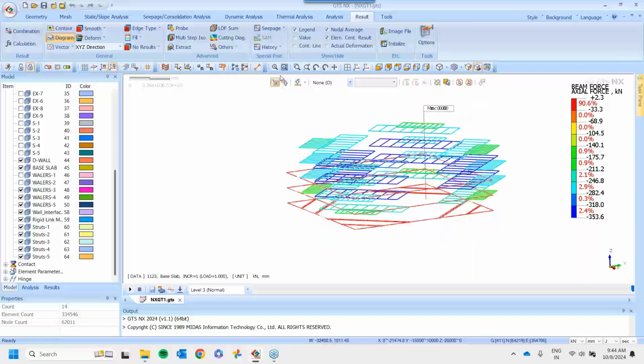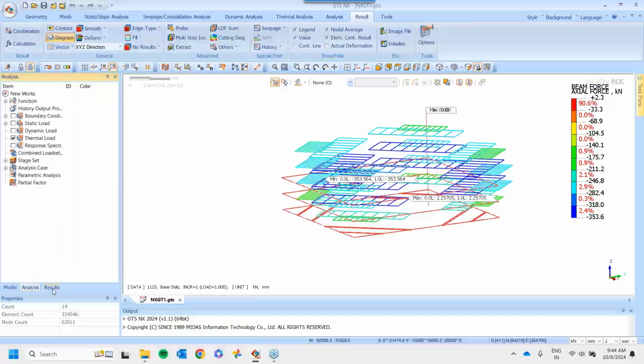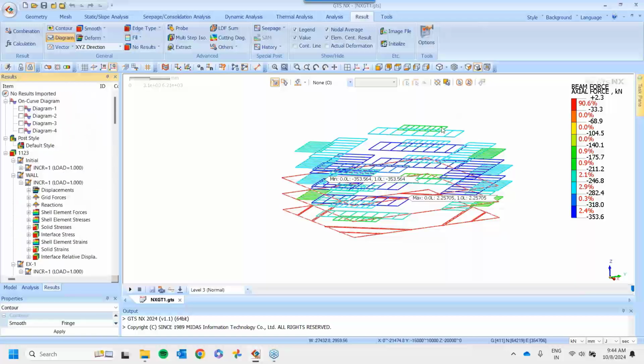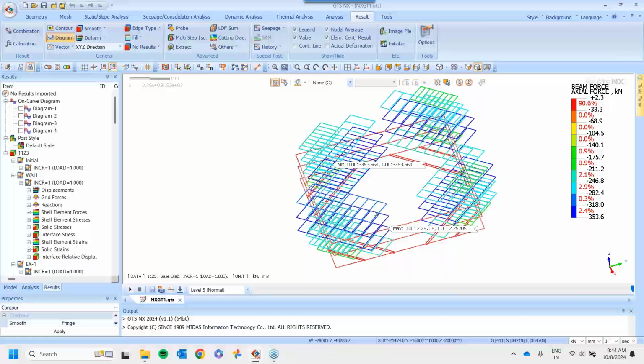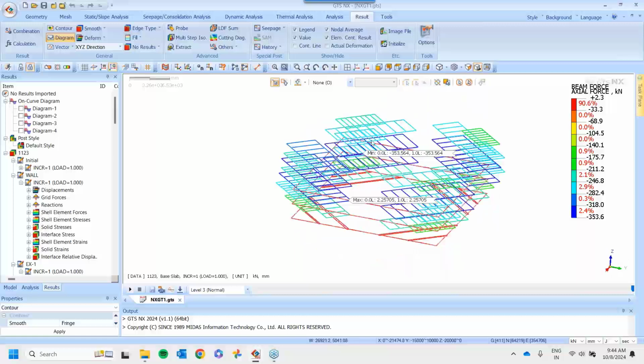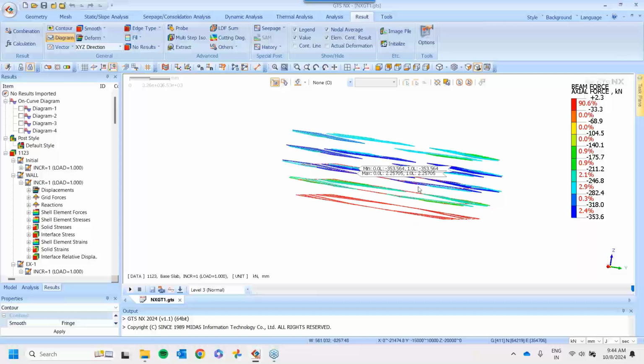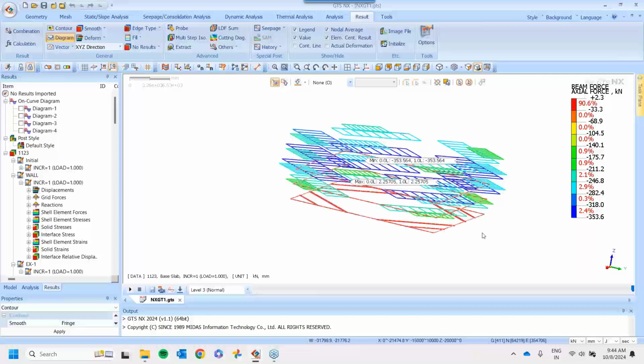You can see here, if I use the value option, the maximum load is along the top, and the bottom we go, the lower is the load taken up by the support system. So one can argue the bottom support system is not required. Yes, that is true. In this case, the bottom support system is not required because most of the load is taken up by the struts and the whalers on the top.